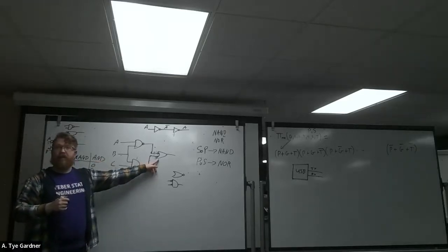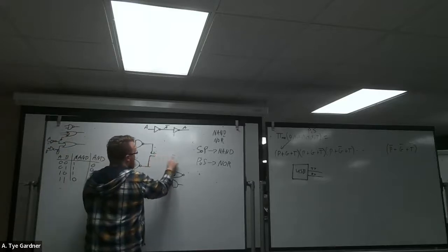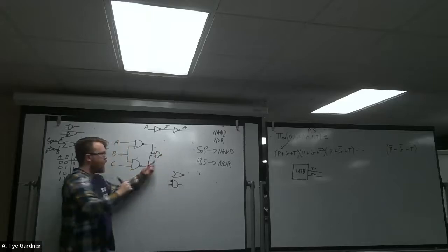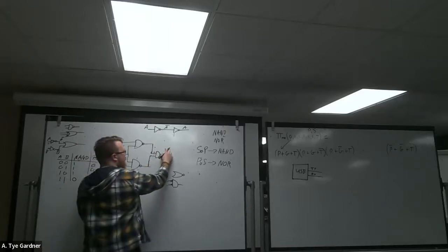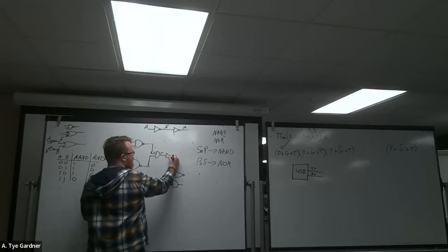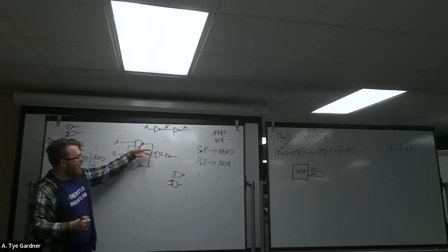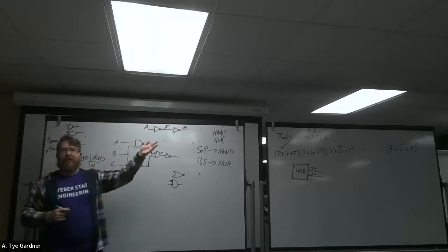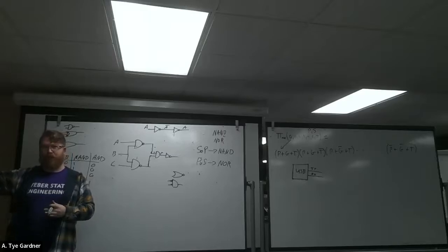This is NAND. So if we push it to the right and change to an AND, well, it takes 2 steps to do that. So step 1 is I flip the gate and push it through. So we're still NAND. It was an AND, it is an AND. And then detach it. And now I can easily turn this bubble pushing again into NOR. This is kind of beyond what you need to know, because I'm just going to have you design sum of product or product of sum.